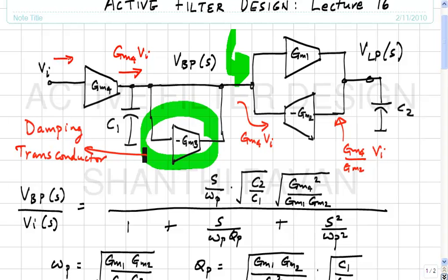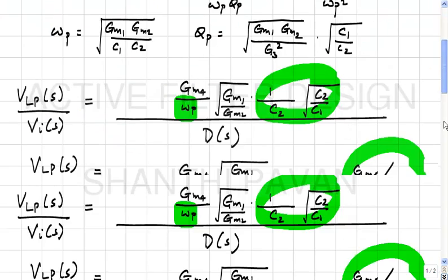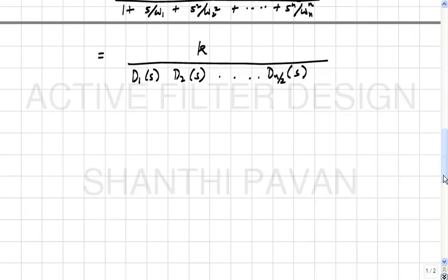So if this is loading another network, no current is drawn. So it should be quite okay to cascade these biquadratic sections. There's no need to put an explicit voltage controlled voltage source between the biquadratic sections.